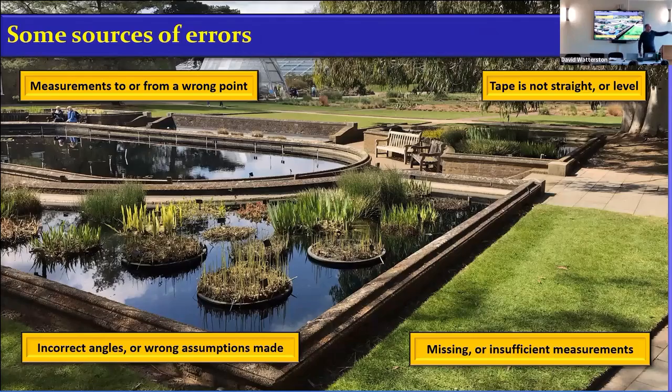If I wanted to measure that gully that's in the middle of that open area out there, but my control point was in the footpath at the other end. If I put it on the nail on the footpath and pulled it over here, if I pulled it down to the gully to get a distance, I've got that angle from the pathway to the edge of the flower bed, and then the angle from the top of the wall down. And when you bring them up to the horizontal, they're going to be different. So when you're plotting it on a plan, you want it to be horizontal.